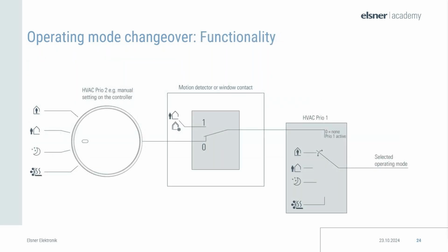As we all know, nowadays energy consumption plays a huge role. So we would like to not only control the heating, but also make it smart. For example, we have the ability to turn the heating on when people are present in the room and to lower the temperature when they are absent for the sake of energy efficiency. Another possibility is to lower the heating when the windows are open. Of course, in winter, we don't want it to heat out of the window. We want to keep the warmth inside, so the heating should turn off if the window is opened.